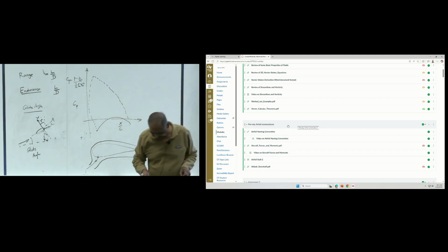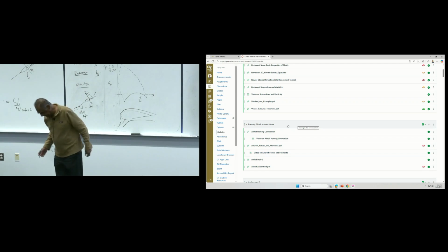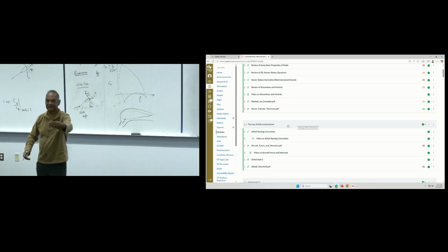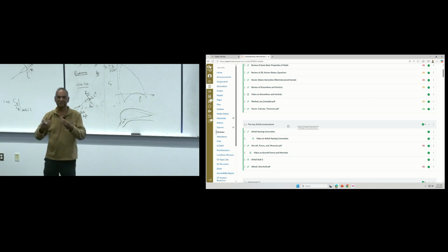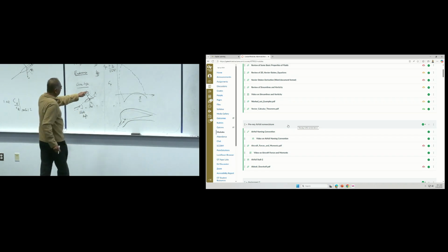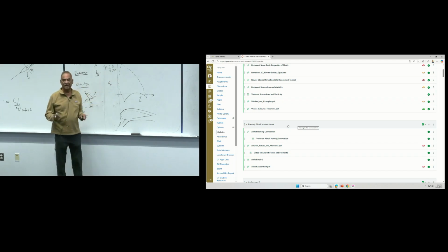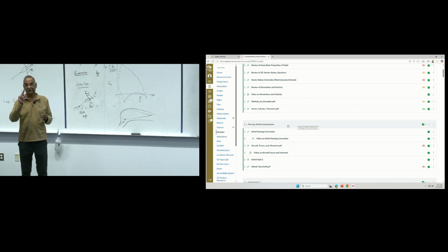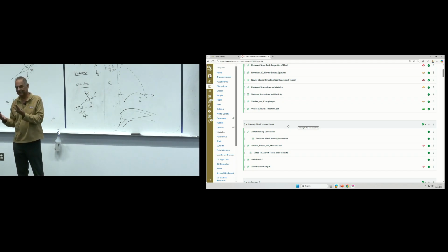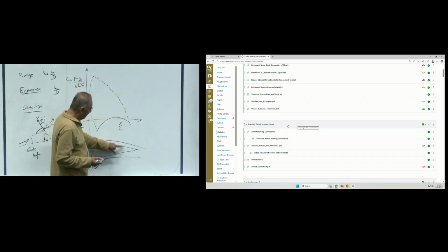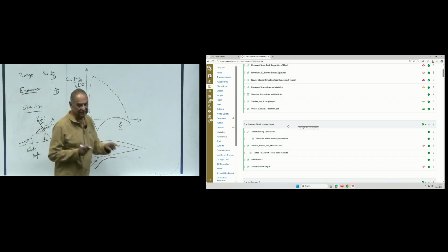Think of a poor molecule moving in the boundary layer. You slow it down by the viscosity, and it also has a higher pressure in the front compared to the behind, so it's pushed back. That's called an adverse pressure gradient. So this is the favorable pressure gradient. As we saw in our last lecture, adverse pressure gradient can cause transition, where flow may become laminar to turbulent. That's one bad thing that can happen. But it could also cause the boundary layer to separate, called a stall.